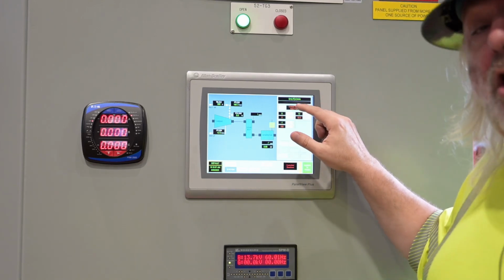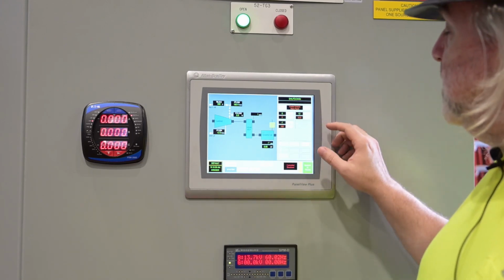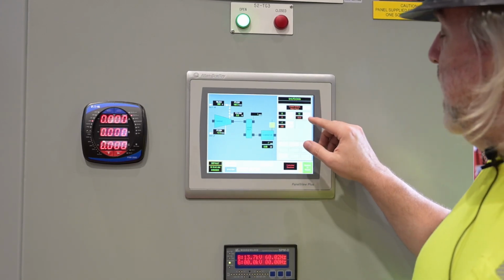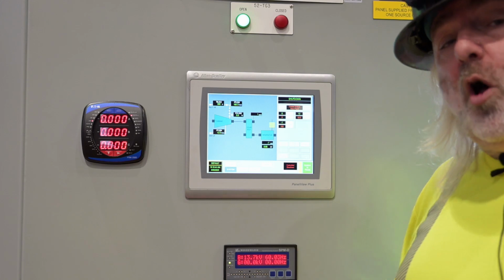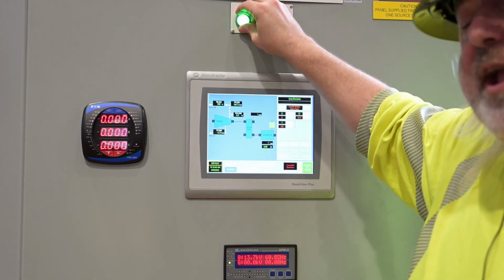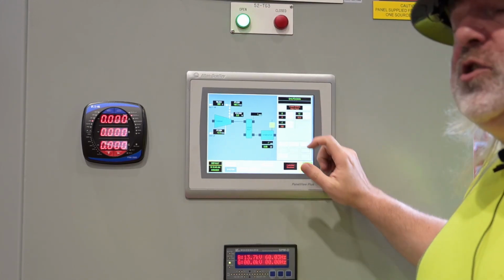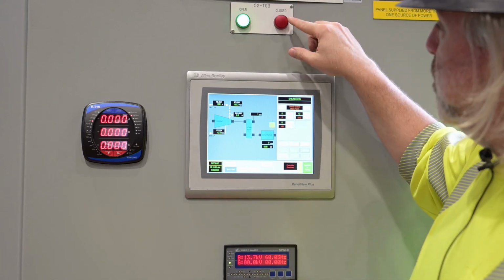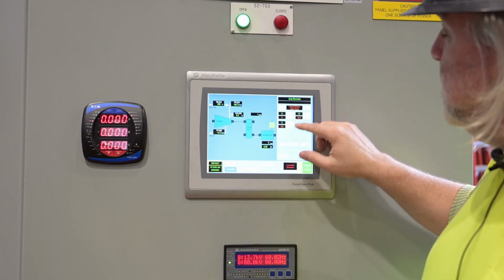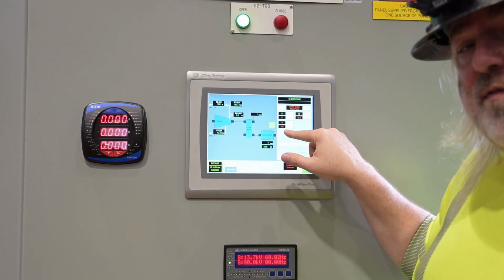Next, we have our control loops. Currently, this system is designed to have speed, exhaust pressure, and kW control the governor valve. With the breaker open, speed will control the governor valve. With the breaker closed, red, exhaust pressure and kW will control the governor valve.